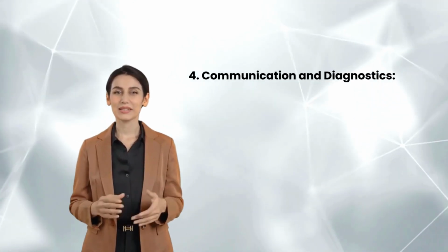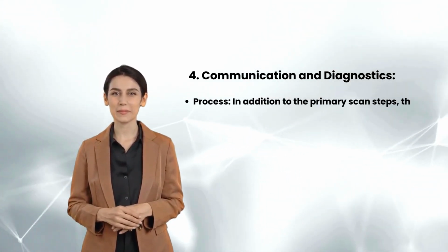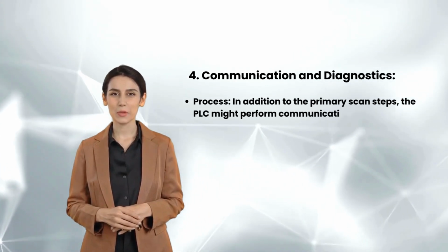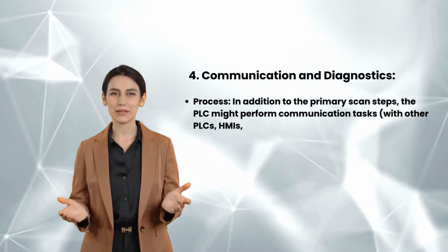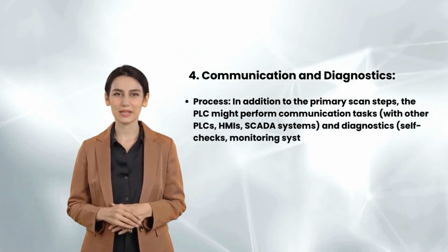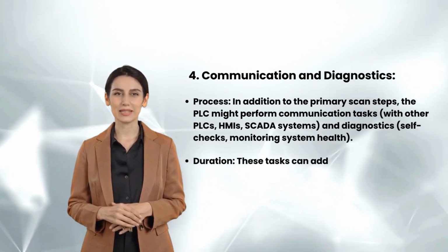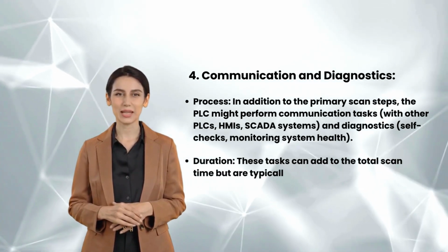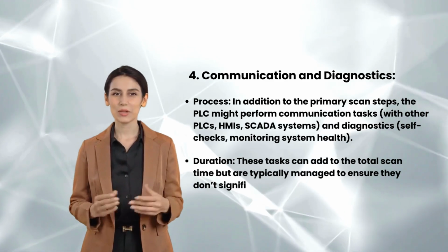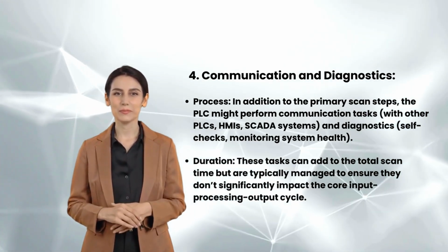4. Communication and diagnostics. Process: In addition to the primary scan steps, the PLC might perform communication tasks with other PLCs, HMIs, SCADA systems, and diagnostics, self-checks, monitoring system health. Duration: These tasks can add to the total scan time but are typically managed to ensure they don't significantly impact the core input processing output cycle.